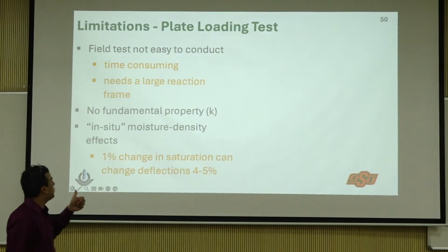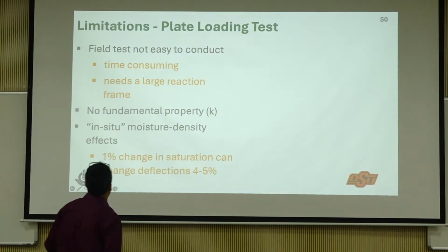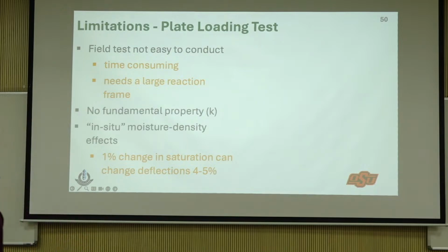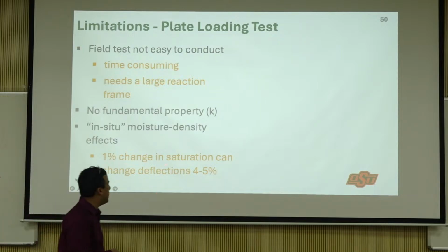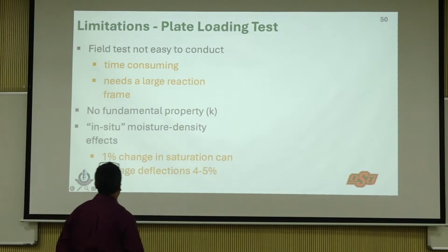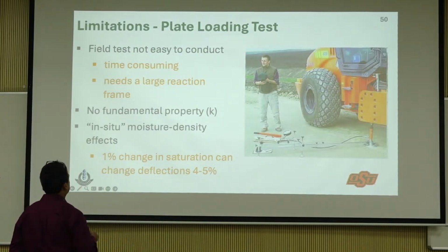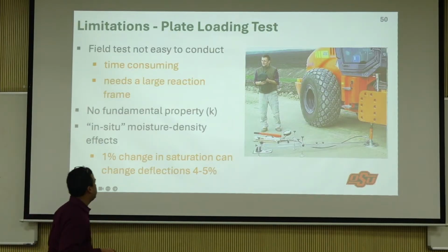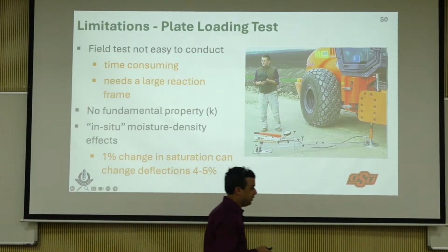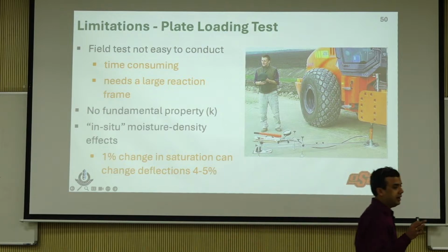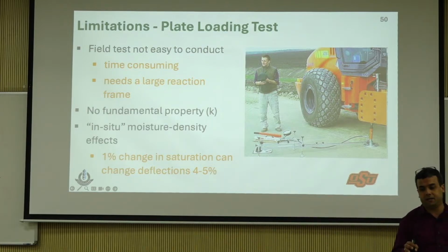Limitations: not easy to conduct, time consuming, needs a large reaction frame. Again, not a fundamental property. It is dependent on a lot of other things: plate diameter, saturation, and you have to really know that there is no plate bending happening. And one more thing I wanted to highlight here is